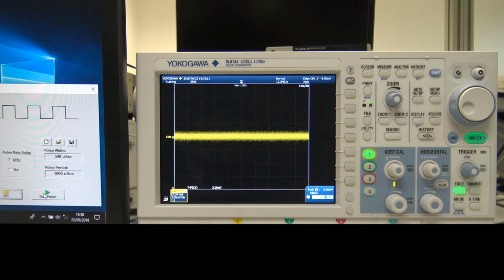It seems that the signal is too weak, and yes, the vertical scale is at maximum resolution. It is at 2 millivolts per division. Obviously I could increase the output power, but just a minute, maybe we can find more elegant choices to see something. I have used the default configuration of my oscilloscope. Maybe I can improve the detection by changing something here.